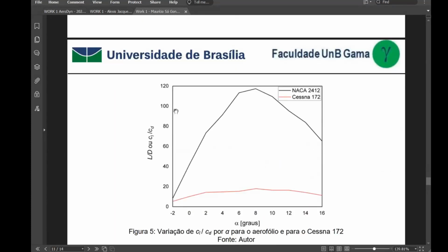Okay, the CL/CD ratio here for your airfoil. I think it's okay, but questionable about 8 degrees. I'm not sure it should be at 8 degrees, but maybe for this particular airfoil. Usually the CL by CD ratio peak is situated more on the left, at 0 to 5 degrees, but not at 8 degrees. Maybe for this particular airfoil it is here.